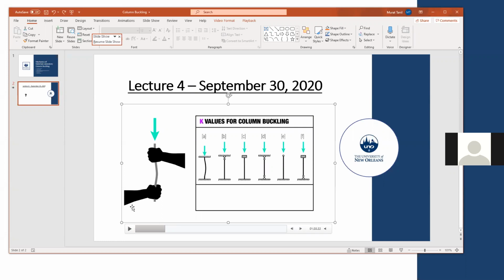It's going to be hard to buckle the column as opposed to a pin connection, because you are holding it in 3 different axes. On B, you have pin connection at the top and fixed at the bottom. You can see on the left side how you have to picture it in your head.